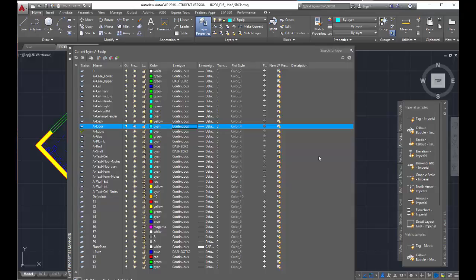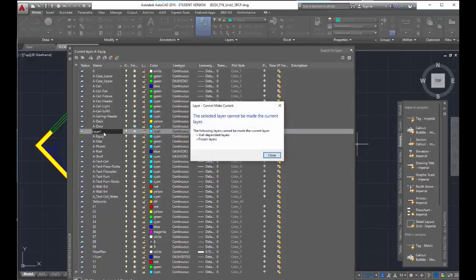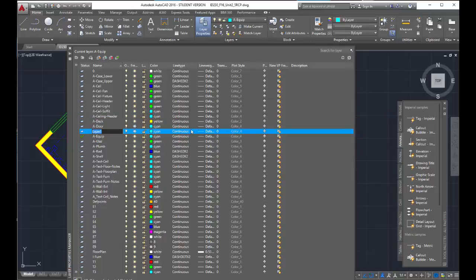So the first thing you should do is enter all of these layers into a new document. So be sure to type units first, and then go to the Layers Property Manager. Click the icon that looks like a piece of paper with a little ball of sunshine on it. That's the Add a New Layer button. And you will see that if I click on that, a new layer forms, says Layer 1. If I double click on the name of it, it allows me to rename that layer. I can decide what color it needs to be. I can decide what kind of line type it's going to be. And that's all there really is to making a new layer.